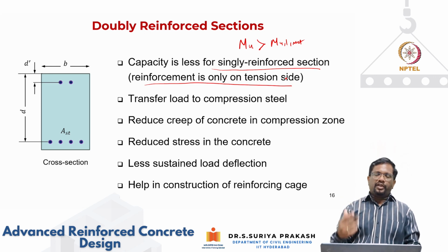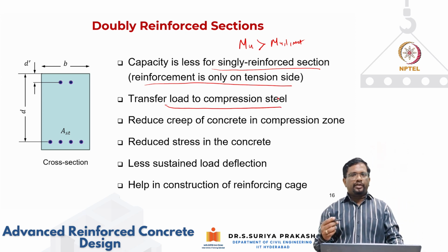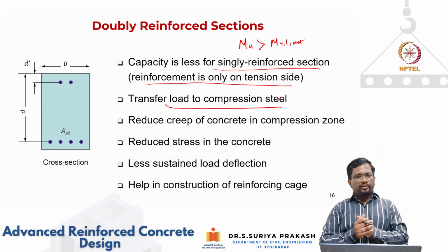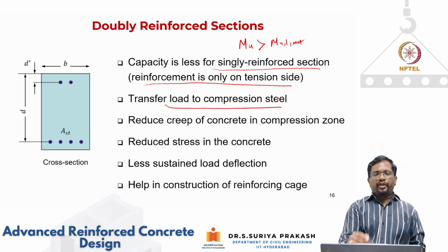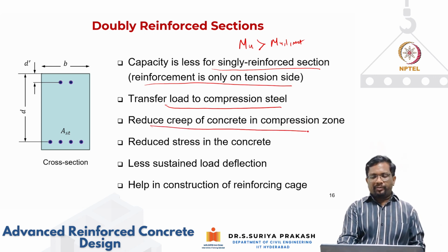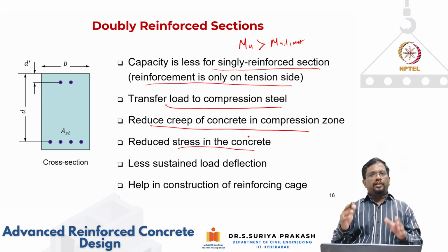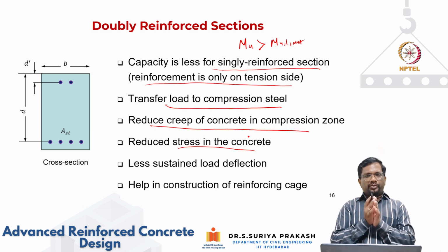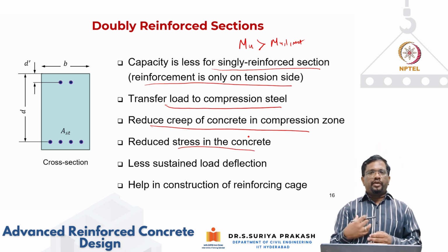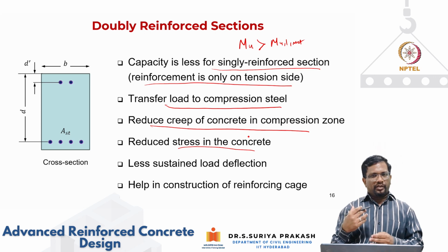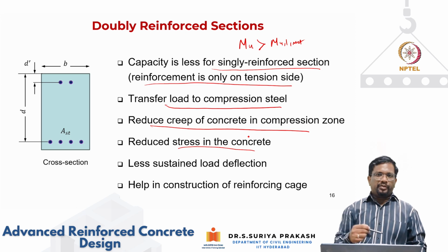Sometimes when we do the analysis, we need to reduce the stress in the concrete and transfer the load to compression steel. This is particularly effective whenever your members are undergoing creep. Putting compression steel will actually help in reducing the creep of concrete, and it is going to help in reducing the stress levels in the concrete under service stress condition. If you want to limit your stress in the concrete due to some design requirement, then providing compression steel will help in reducing the stress levels in the concrete for a particular service moment, right?